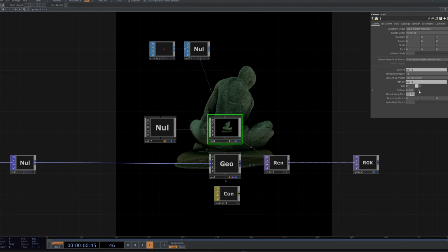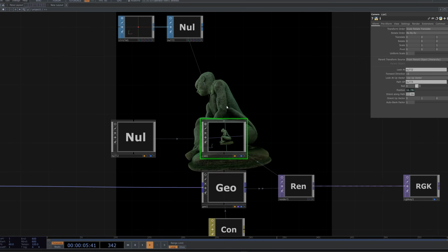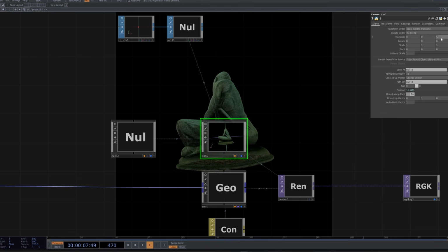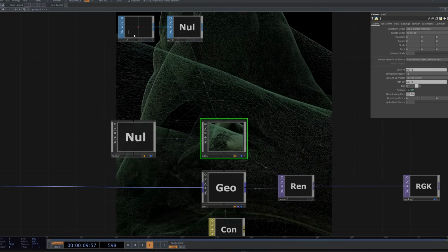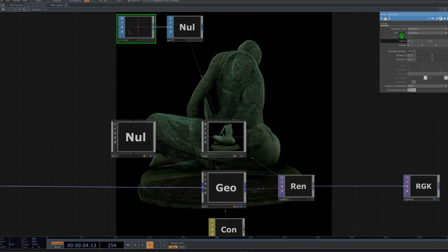And so now if I change the position of my camera, it's going to turn around my subject. So I'm going to use the expression absTime.seconds and multiply by 0.05. And I have a slow, slow rotation. In the translate, I'm going to choose 0 here, and I'm going to increase the radius of my circle.